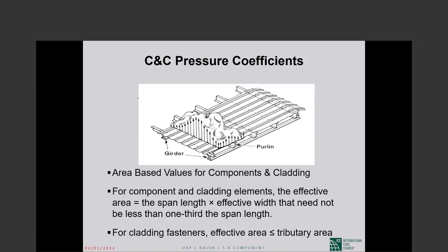There are times, like a roof truss, when we are not sure whether it's a component or part of the main wind force resisting system. In those cases, the best advice is to treat it as a component, and treat it as a main wind force resisting system. Whichever way you get higher wind pressures to design for is the way to go. Okay, so now